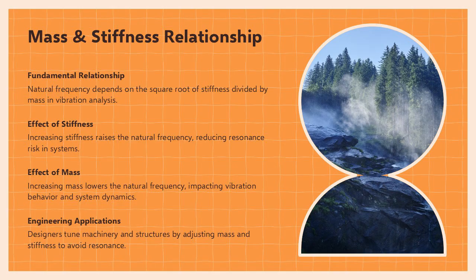Applications include tuning machinery away from excitation frequencies, adjusting system mass distribution during balancing operations, and reinforcing structural components to increase stiffness. The content also highlights how engineers model mass-stiffness dynamics when analyzing complex equipment or plant structures to avoid resonant conditions. Understanding this relationship supports proper engineering judgment for corrective action selection.